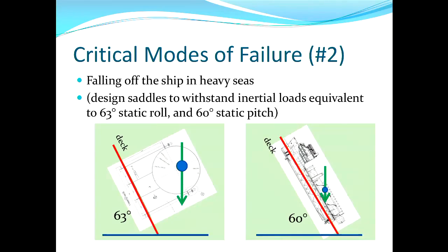Secondly, getting it there, it would be really serious if the prill tower fell off the ship while it was being transported from Indonesia to Australia. So you've got to consider what are the most serious but realistically likely sea conditions that the structure will have to withstand when it's lying horizontally in its cradles on the ship.